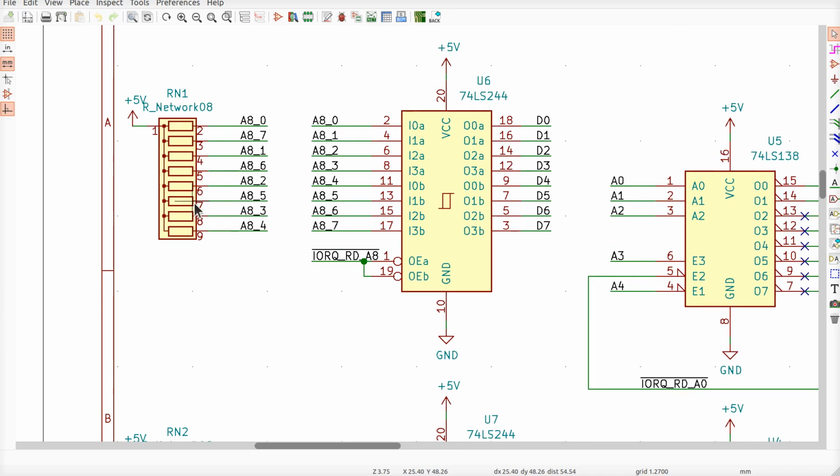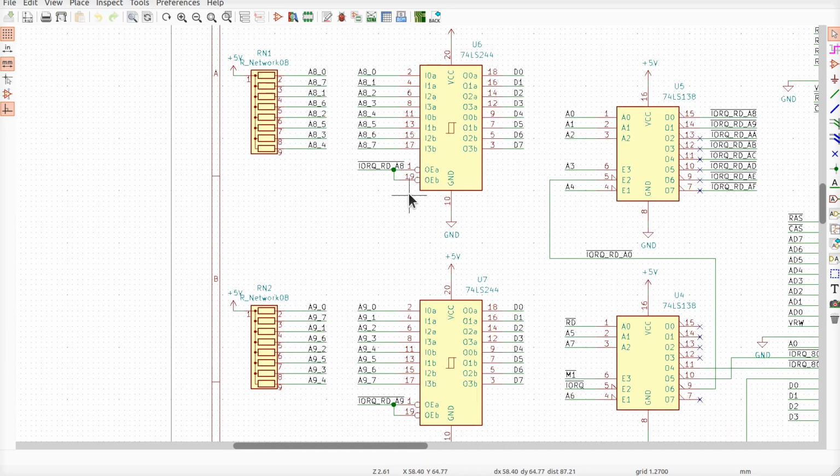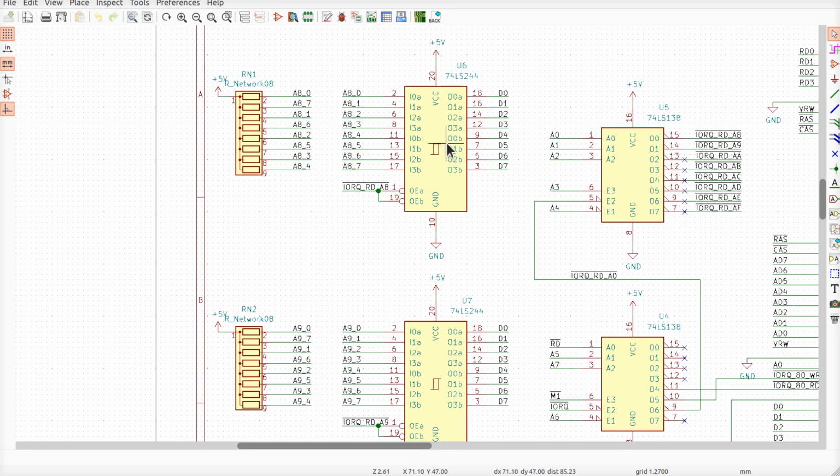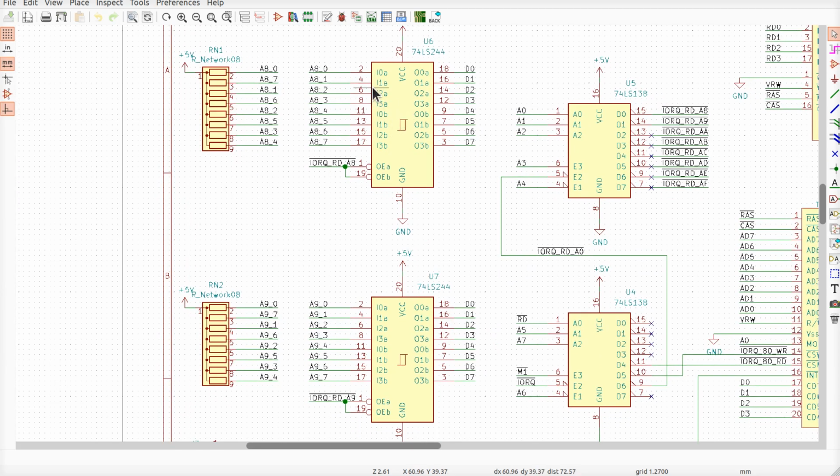But I cannot stress enough, I have seen it, I know it happens. Even with this, it's not like, oh, this one LS192, 75 doesn't. No. Two chips with the exact same number from the exact same manufacturer, I have seen act ever so slightly different. I think it was a flip-flop of some kind, or a JK latch or something like that, where one of the inputs, like the reset input, when floating was not necessarily acting as though it's high all the time.